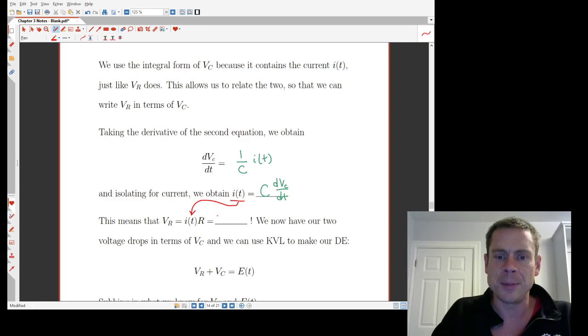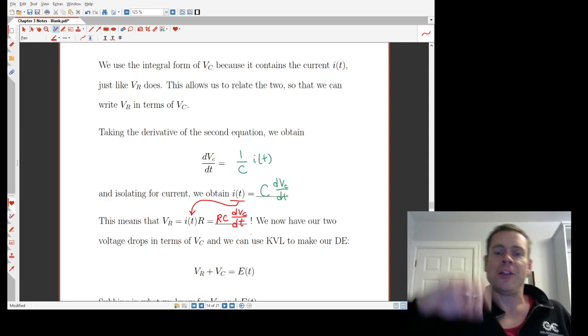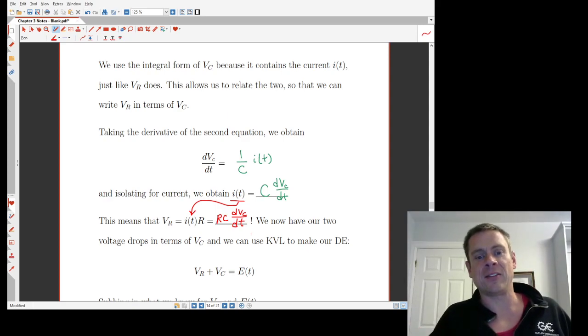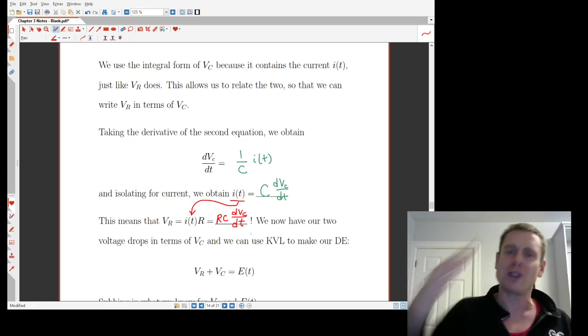So maybe I'll write RC. And then the I here is going to really just be the C that I just wrote times dVC by dt. So essentially, the reason I'm going through all of this is because, well, I have VC, but now I have an expression for VR that's in terms of VC.